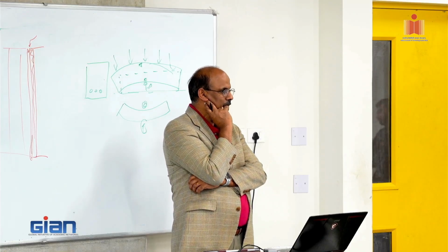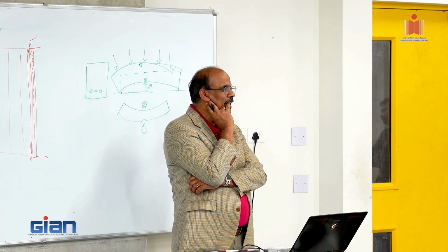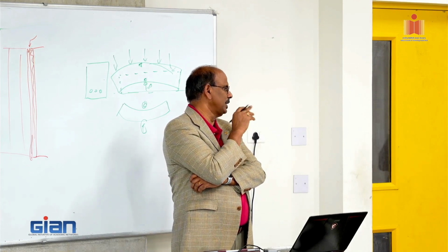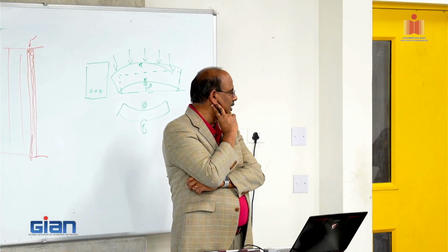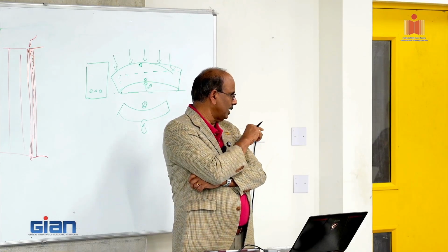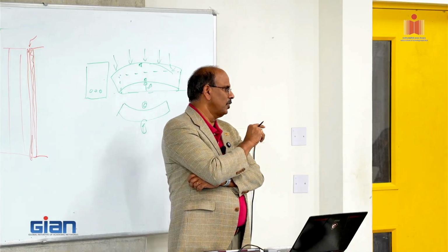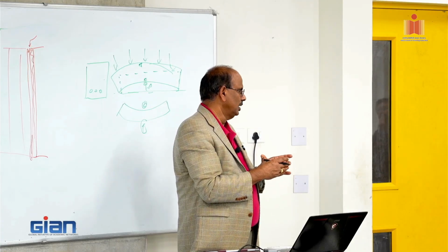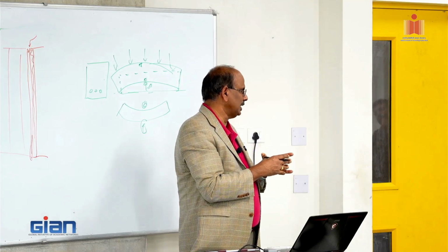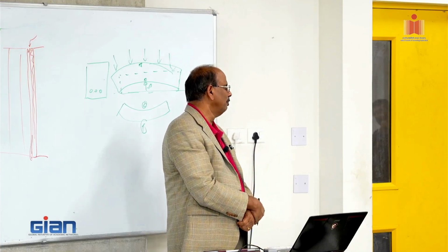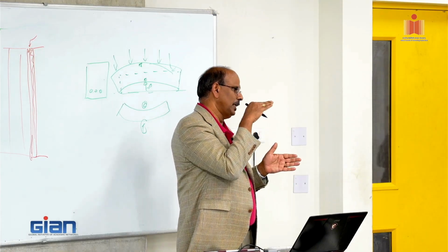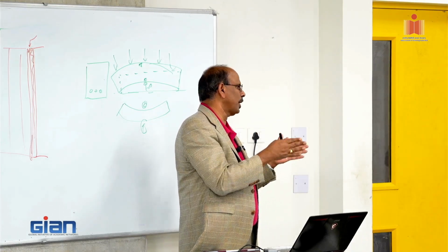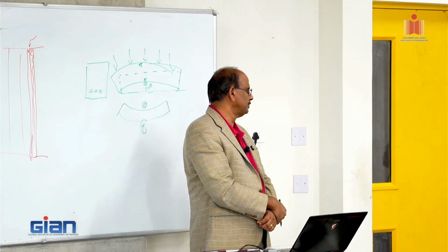No, I think he misunderstood that as the epoxy that we use in FRPs. Oh, no. It's a cement base, right? Everything is cementitious. So even if it cracks once, whenever it is loaded, that's something. Crack where? Within the interface? Typically those grout pads are made out of non-shrink fiber reinforced grout material. So when it hits, like if you end up rocking for example, even if it cracks, it won't break away. That's the reason they use fibers.